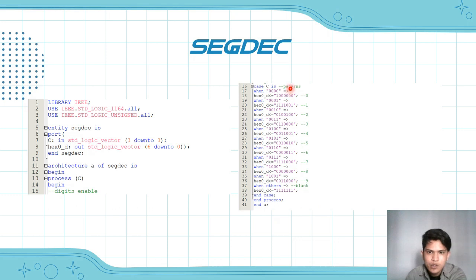In case the value of C is 0000, then H0D will be assigned 1000000. And when C is equal to 0001, H0D will be assigned 1111001, and so on. In case C has other values, then H0D will be assigned 1111111.